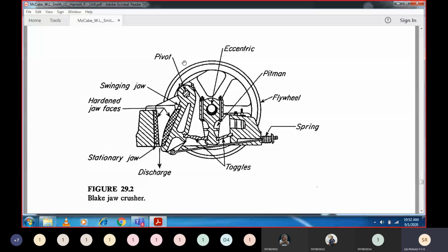Remember, what is the function of the flywheel? This is designed for coal ore. For example, we have ores of coal that you can put in. But suddenly if somebody puts in some material whose compressive strength is very high, it will enter the system, but crushing will not take place, because the entire system will lock as it is not able to apply any force, but the machine is running. Under such situations, this entire setup will go back. The relief spring will be released, and this toggle, this connecting rod, will go back. Then because of gravity, the solid material will fall and go out of the system. But what will happen to the energy given to the motor?